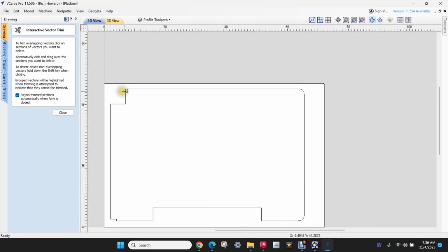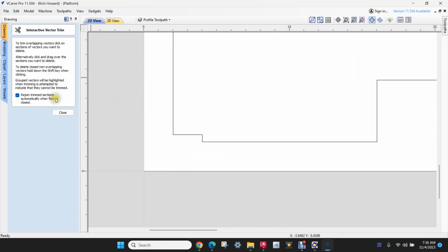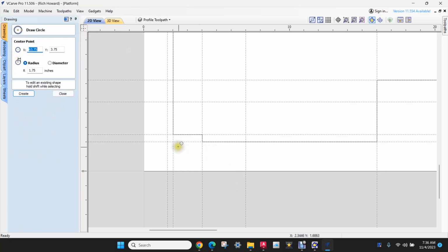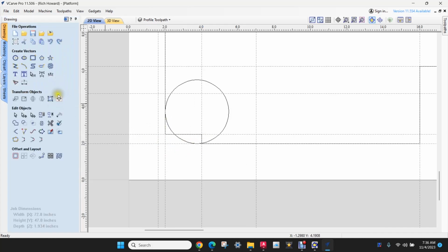Right on. So this is all getting cut out here because of that large conduit. So let's go down into this corner and make one here. Bring back our guidelines. Bring back our circle. We're going to want it to be here. So it's going to be 3.75 on the Y, and then the X is going to have to be 3 3/8. That's about right. Close. Let's trim.